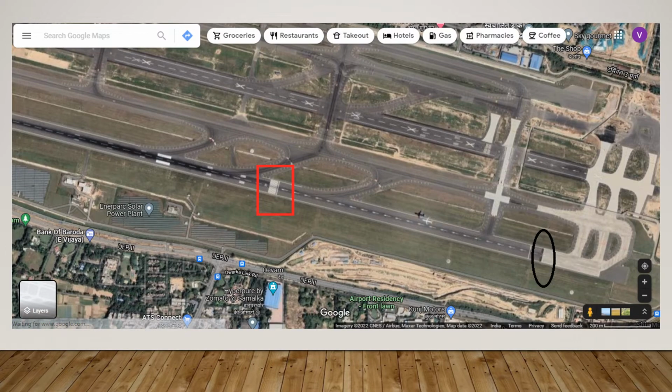In the next slide, I show a point where the runway is starting and you have a displaced threshold. That is a threshold which is not located on the extremity of the runway. So in the previous slide, you see the runway is of such length that half of it is being displaced due to the growth of obstacles. This may have an impact on the effective utilization of that particular runway.